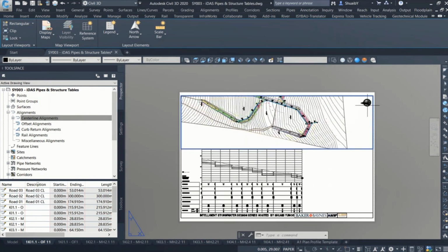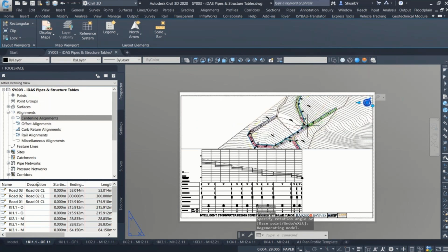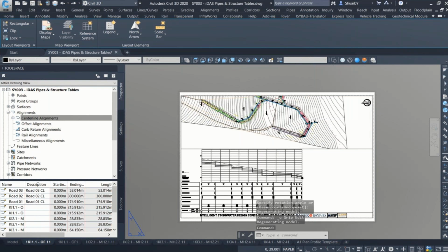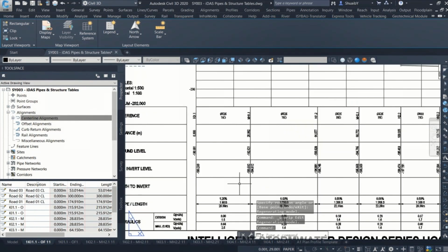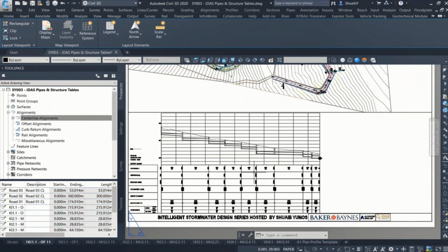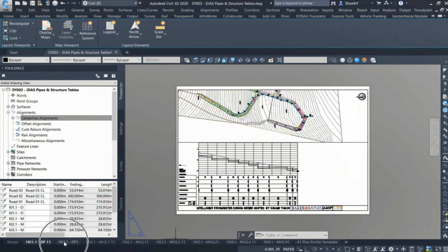And the cool thing is the north arrow is also there. So I'm going to show you that the north arrow is actually configured to your positioning on site. If I have to move this, I do not recommend fiddling with this, leave it as it is. But if I change it, you can see that the plan updates relative to the north arrow. So I'm just going to undo that. But yeah, you can see it sits in great. All of the sheets are generated.